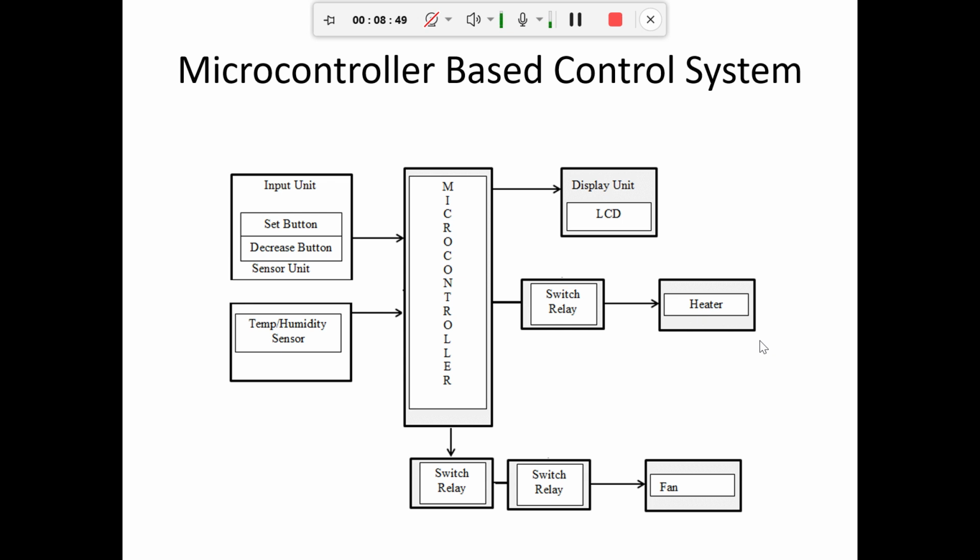In the microcontroller you can directly connect input and output devices. You might have seen the Arduino board, which uses a microcontroller inside. If you want to interface a switch, you can directly interface it. There is no need for a separate port. Like that we can connect input devices and output devices, and output devices operating at 5 volts can be connected directly.